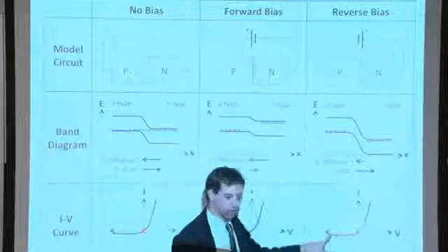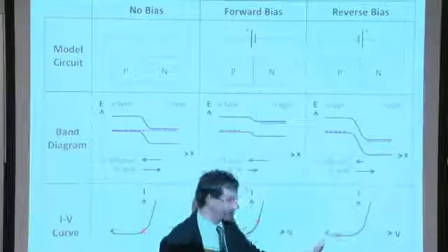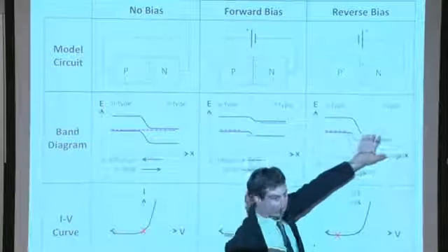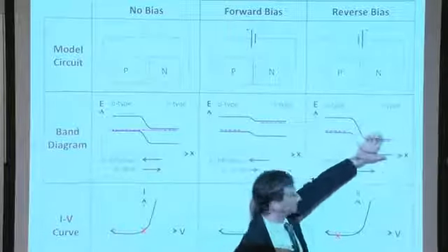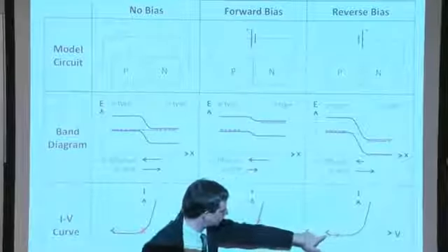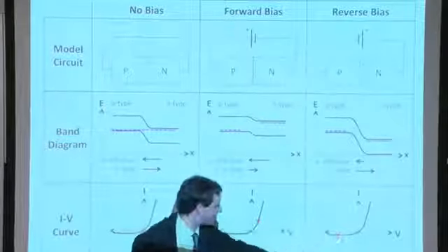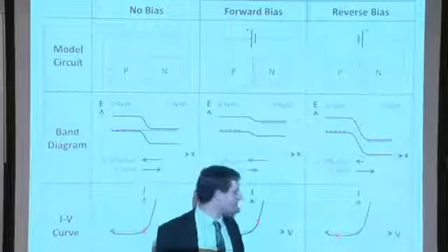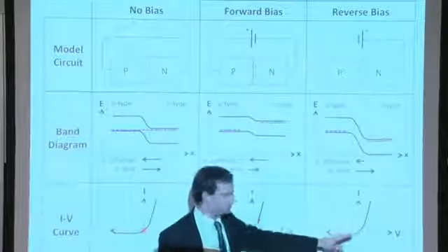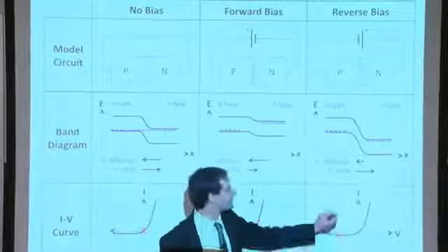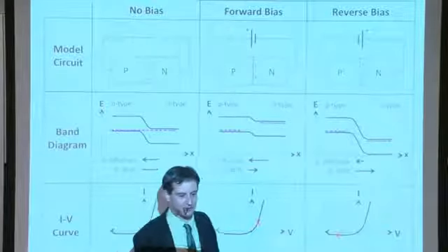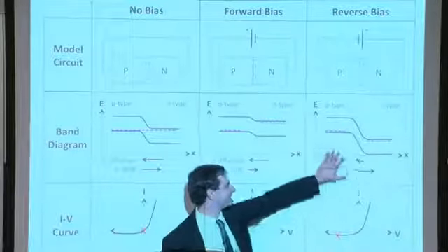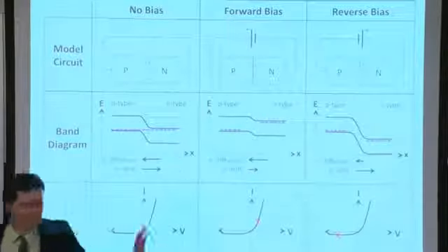Now, this is a very ideal condition. What happens in the real world is that at some reverse bias condition, you have biased it so much that electrons will be able to tunnel through from the p-type into the n-type right here. The electrons in the valence band will be able to tunnel through into the conduction band. And what happens in this IV curve is it goes zoom, begins dropping. So if the reverse bias current, or the current at reverse bias voltage, is not low enough, in other words, if the p-n junction is not strong enough, you could have a catastrophic failure of your module by just shading one of your cells. Thankfully, this is one of the tests that are done with the solar simulator to prevent that failure mode.